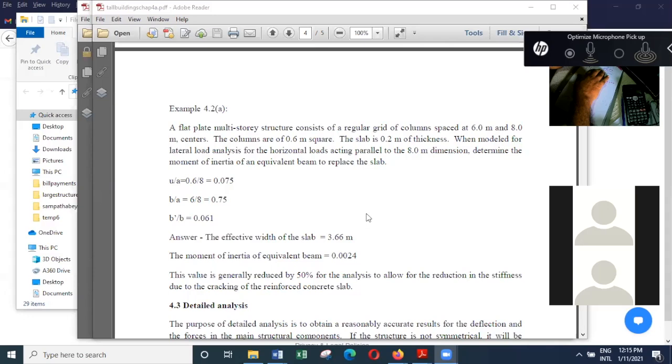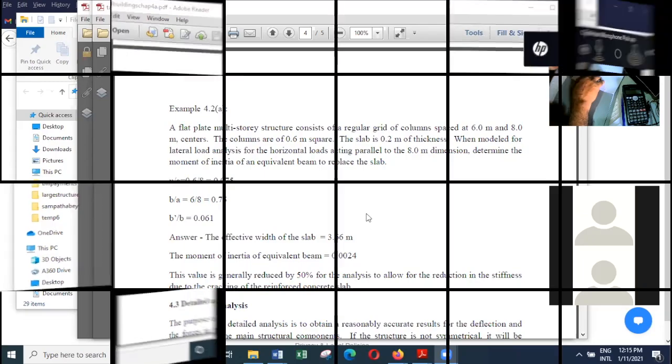Do you have any questions on these minor things that we discussed now? Like representing the wall as a column, and then to represent the actual dimension of the wall, how to use the rigid arms, and also the importance of considering only the important effects when you are doing the modeling.